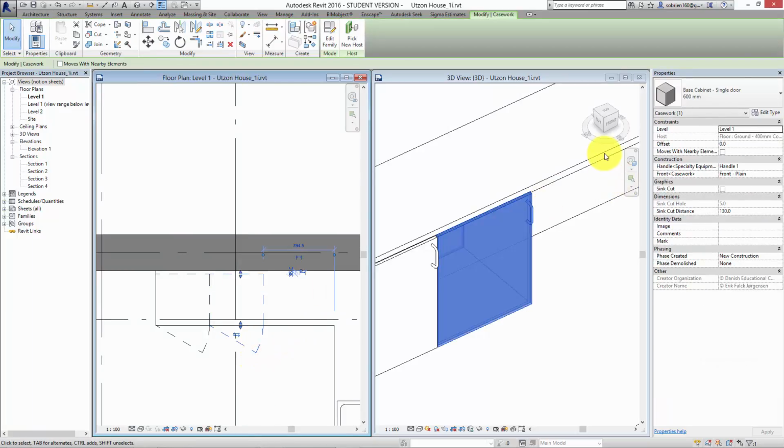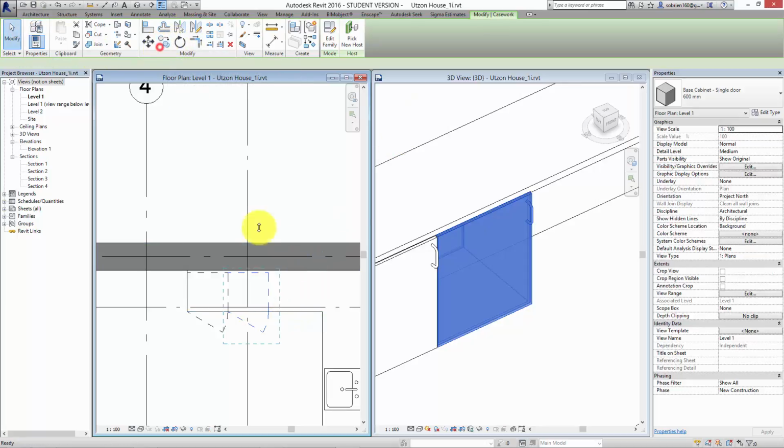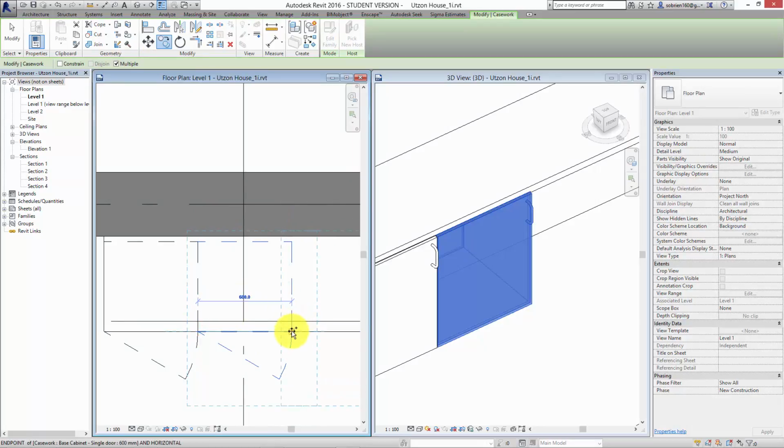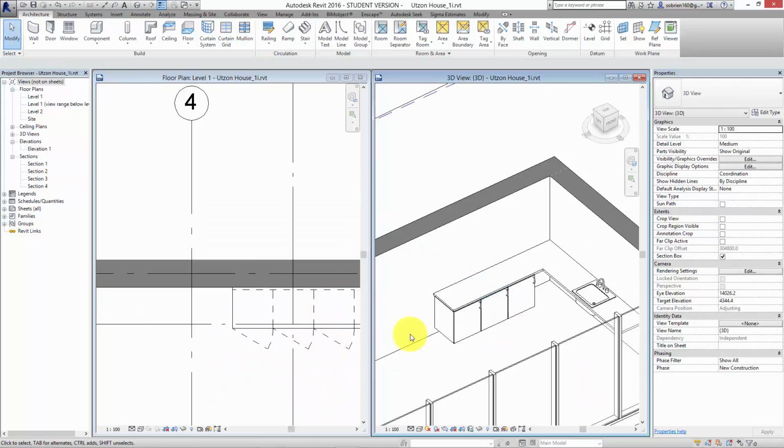So these cabinets that come as standard in the templates, you can also go on to BIM object, or you can go on to Revit, where you insert the other elements and download real kitchen cabinets from real manufacturers, which will come with all the parametric information that you need to use them. Okay. So you can continue around and fill in the kitchen cabinets here.